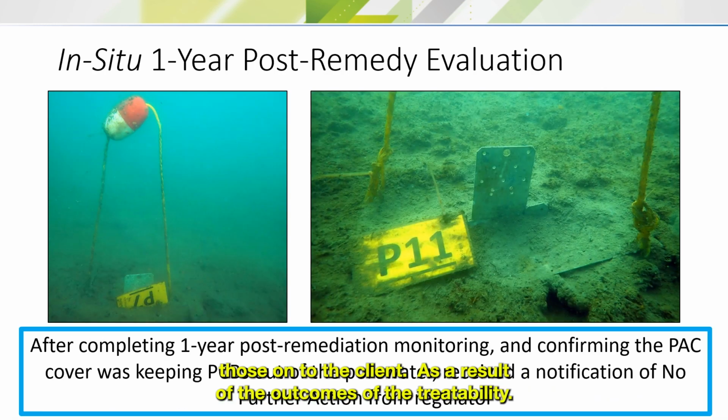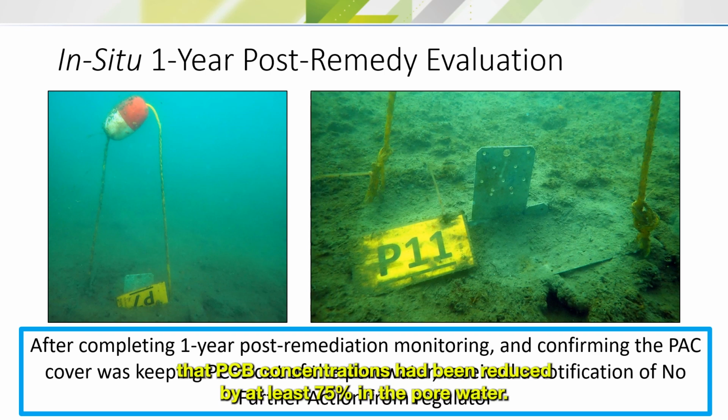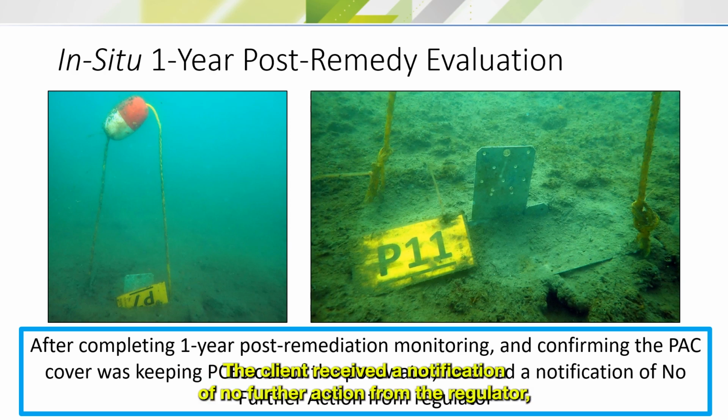As a result of the outcomes of the treatability study, a sand cover with a 3% PAC dose was applied at the site. After a 1-year post-remedy monitoring event was completed, confirming that PCB concentrations had been reduced by at least 75% in the pore water, the client received a notification of no further action from the regulator, effectively closing the site.